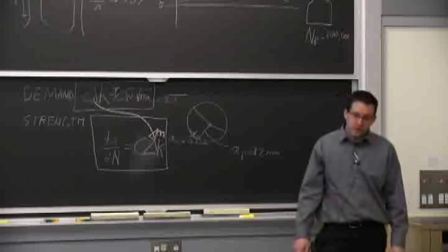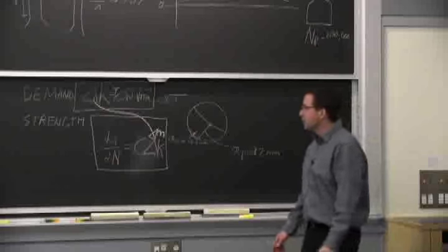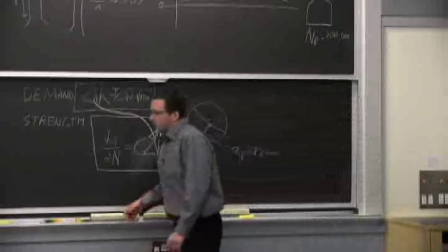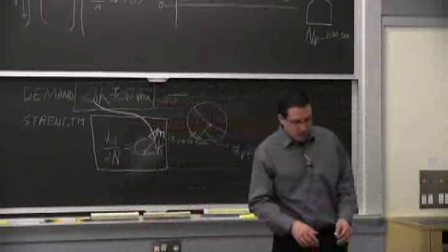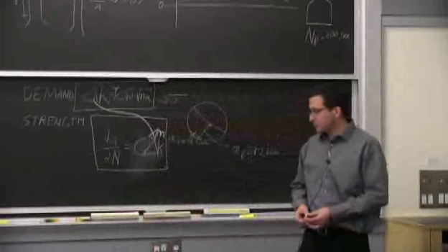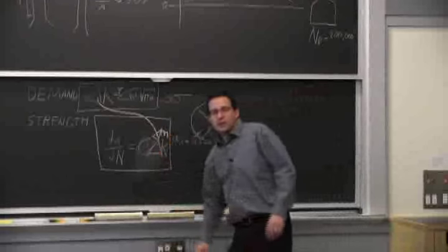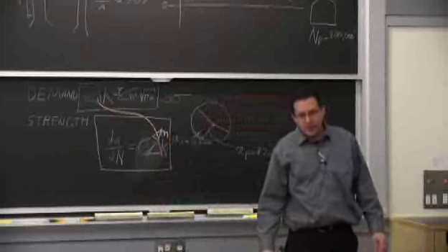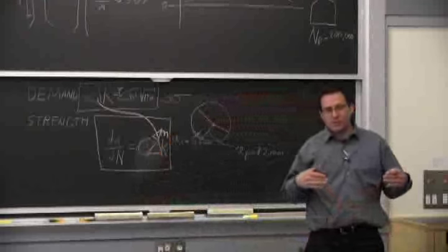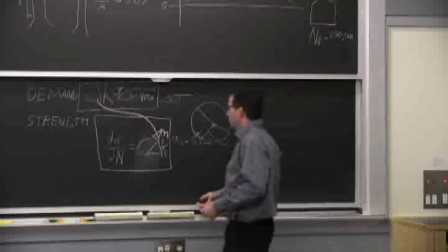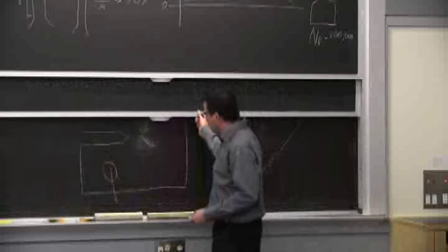What we also do, if we want to create this type of curve, the Paris equation curve, and get those coefficients for a polymer, we can keep track of the crack when we're doing our test.